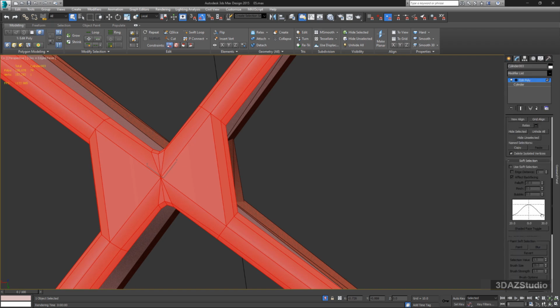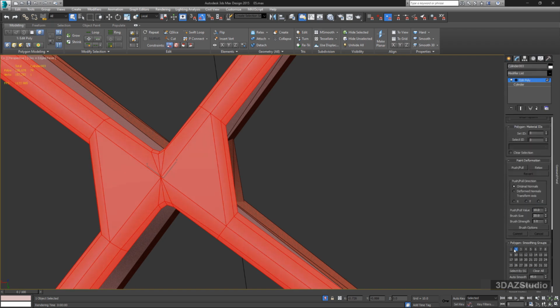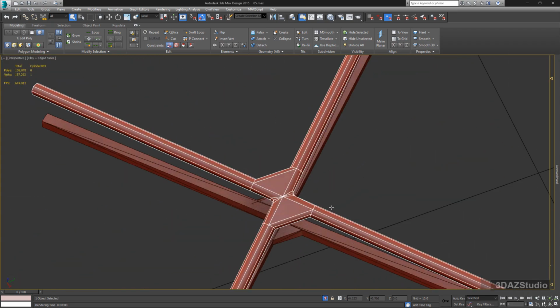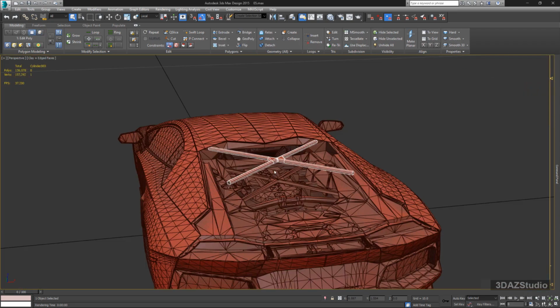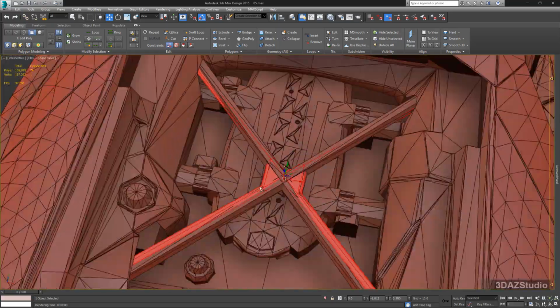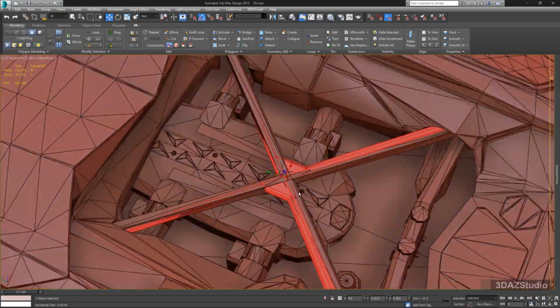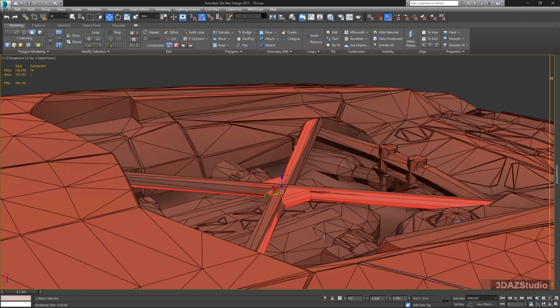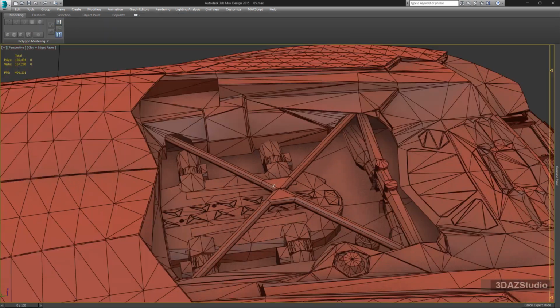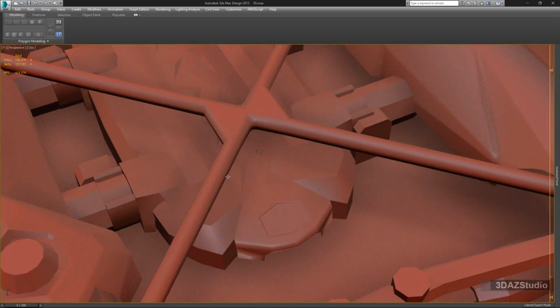Now let's correct the smoothing groups. Select all polygons and, in the smoothing group section, assign group 2 to them. This will give the mesh a smoother shader appearance. Use the Move tool to align the cage to the desired position. To finalize the design, apply a Turn to Polys modifier and limit the faces to 3. Adjust the bottom side of the cage as needed.